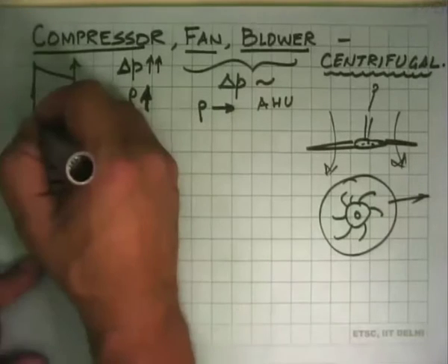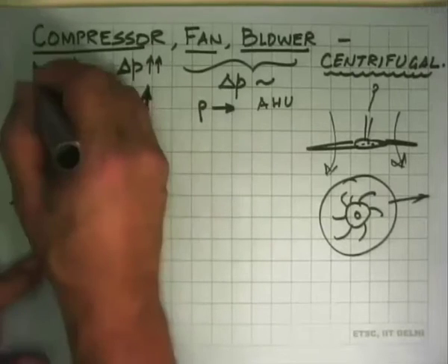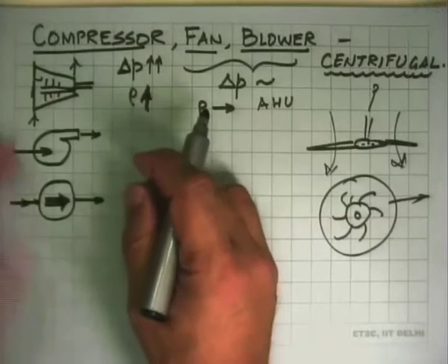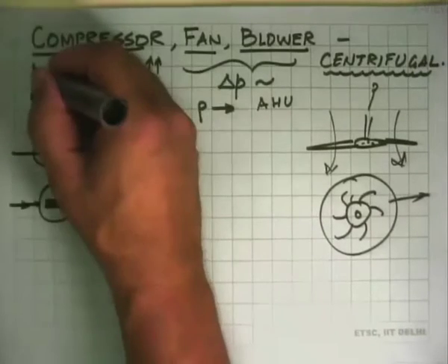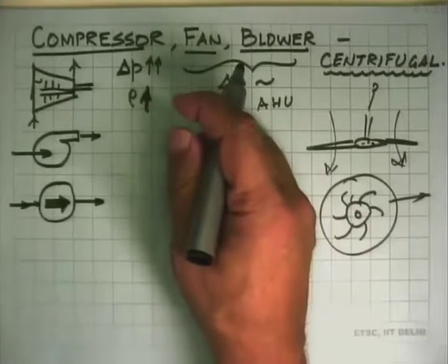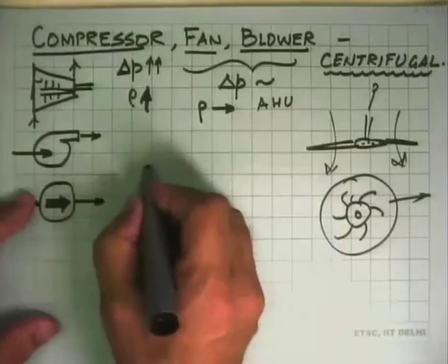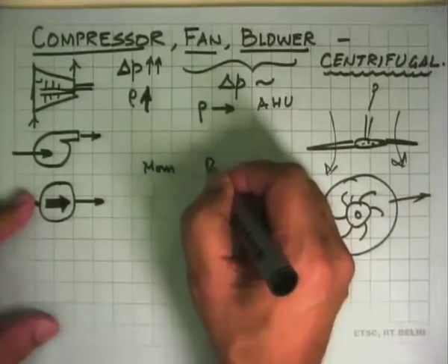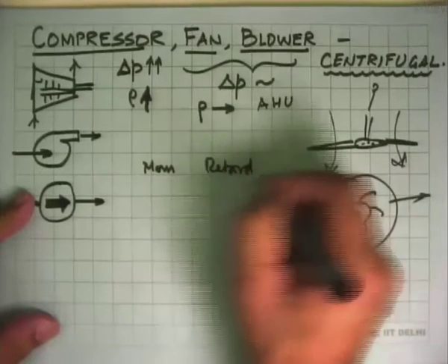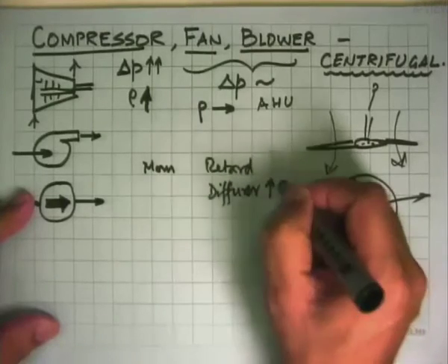In making schematic diagrams, we use three symbols over there. So this means that the gas or air goes in. Inside this, there is a shaft on which there are blades. The air keeps flowing over this, or the gas keeps flowing over this. There is a rotatory part which will give momentum to the gas, and a stationary part which will reduce the kinetic energy and increase the pressure without any work input or heat input. Then the next stage will do it a little more. So like that we do the compression. First we give momentum, so of the energy, and then we retard it. When you retard it, it's like a diffuser basically what we have, and because of this the pressure goes up.